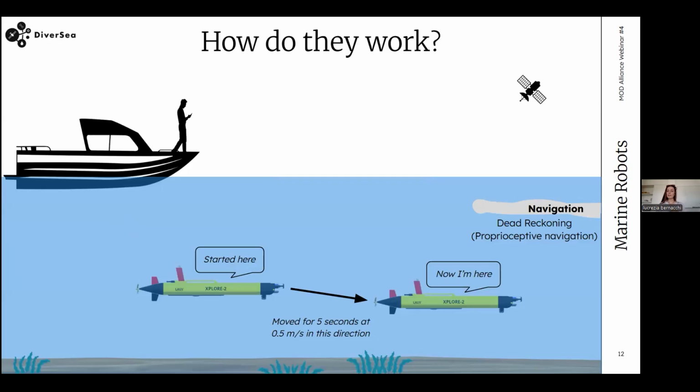Okay. Regarding the navigation, underwater navigation is a very complex task, and there are different methods. Some are based on acoustic positioning, and what we are going to see right now is just the dead reckoning technique. So the logic of dead reckoning is that the vehicle estimates its position, so knows where it is, just using the information of the sensors that it has on board.